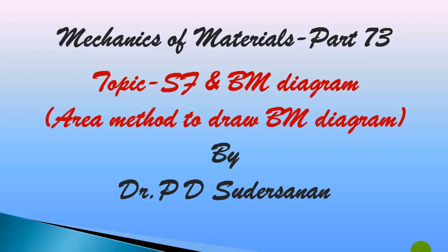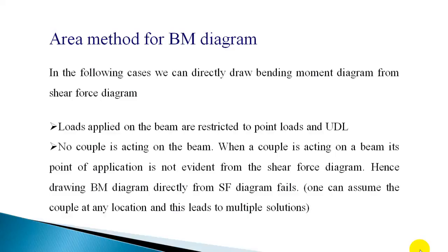In today's class, I'll explain a method to draw a bending moment diagram directly from the shear force diagram. In this method, we draw the bending moment diagram by calculating the area of the shear force diagram. The method is suitable only when the beam is subjected to point loads and uniformly distributed load.